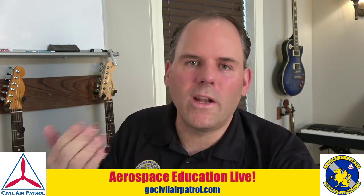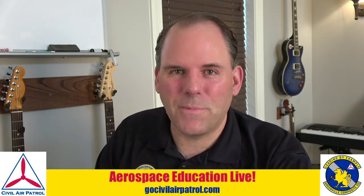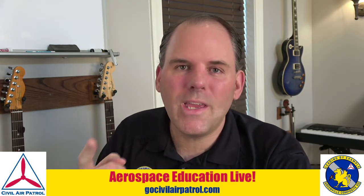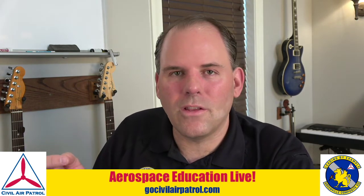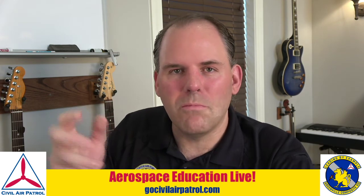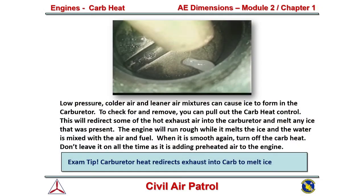And then what you want to do is you want to turn off the carb heat. You don't want to leave your carb heat on all the time. Now I come from an area that's very cold, and so we would be in a bad habit of turning that thing on sometimes because we would really be worried about carb heat. But it does two things. One, you're adding preheated exhaust heat into your engine. That's not good. You want to keep your engine cool if you can. It runs better. And then the other thing too is because you're adding a lighter density air, your mixture is going to be different, and it actually messes up your fuel ratio.